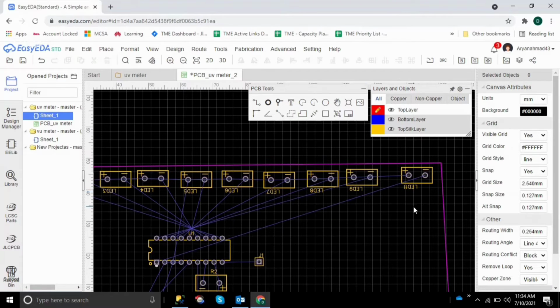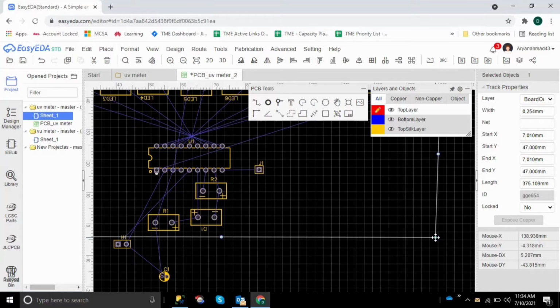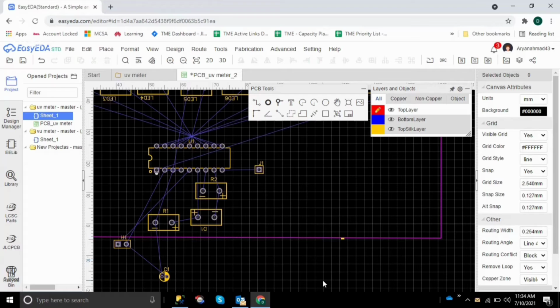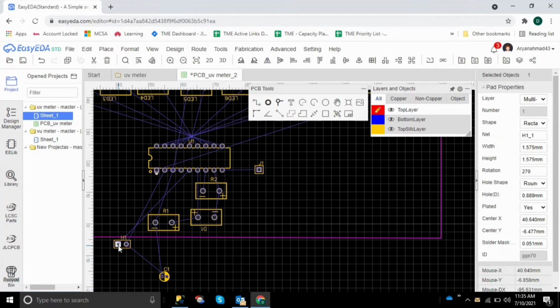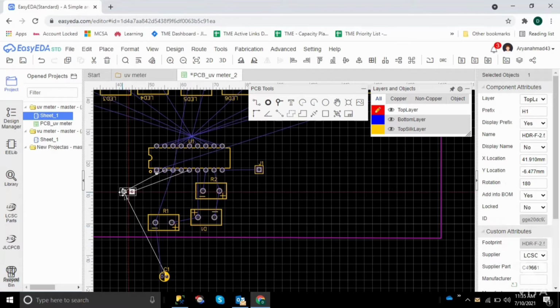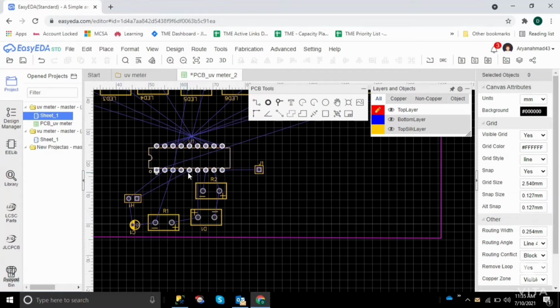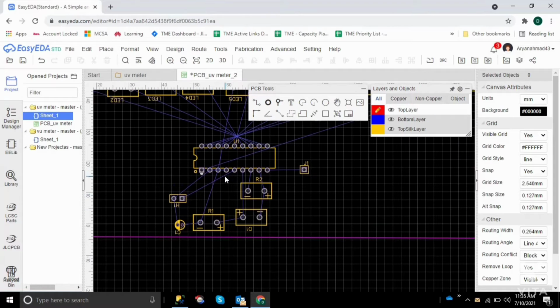Now place this node back in line properly without any curve, and then we place this jumper in here, and then we place this capacitor with proper polarity, such like that. Now make sure there are two tracks that jump to cross this pin number 1, I mean this one and there.